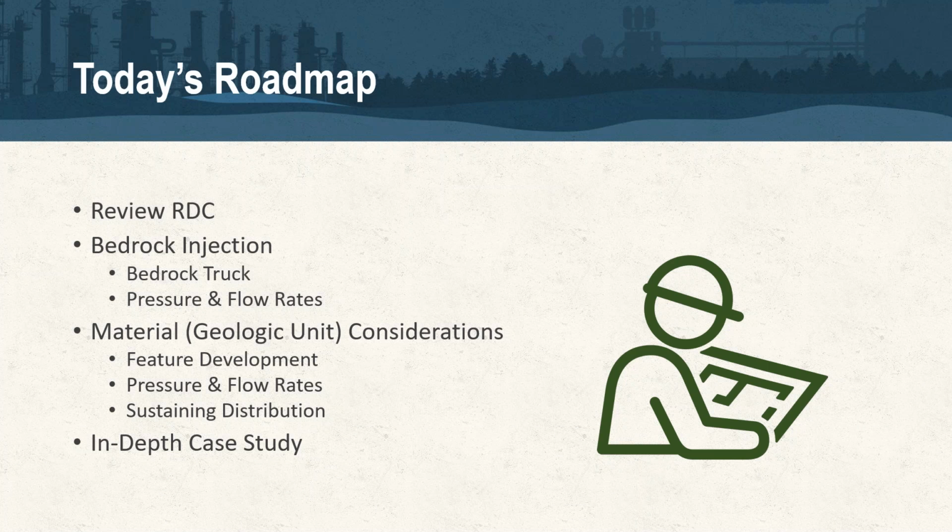So here's our roadmap for today. I'm going to briefly revisit the RDC because that's how we move into the injection design. We're going to talk about the injection itself, geology considerations, how we actually get material suspended and flowed into fractures, features, secondary porosities. And once those have developed, how you sustain them. These systems are not off the shelf. They're custom packers, custom pumps, and they take experience and knowledge on how to run them, which our group certainly has. And Bill's going to transpose that into an in-depth case study at the end of this to show you an example of how this all comes together from this week and last week.